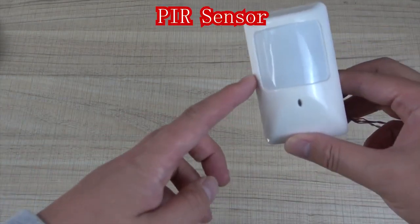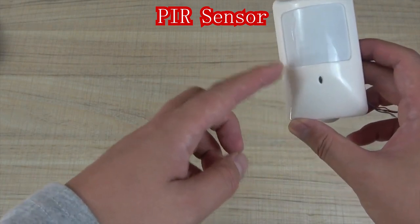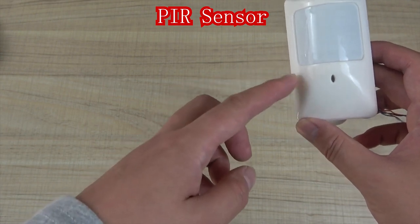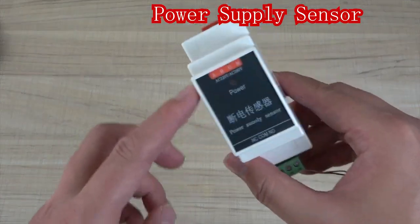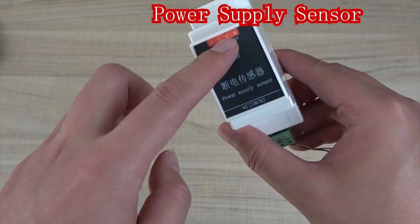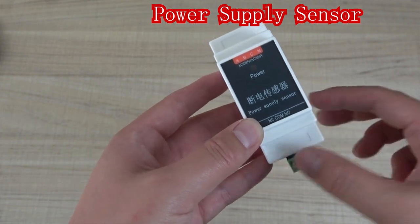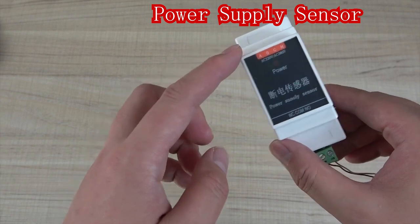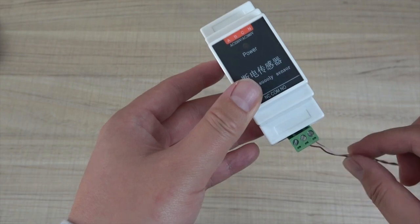And this is a PIR sensor. It's a human motion sensor. It just detects whether there is a human or somebody in your home, in your room. Use this. This is digital output. And this also is useful. This is a power failure sensor. You can see this is A, B, C, and N. So it can detect whether the power has failed. If you have 3-phase power, for every phase, if the power fails, it can detect it. This output is a digital signal output.